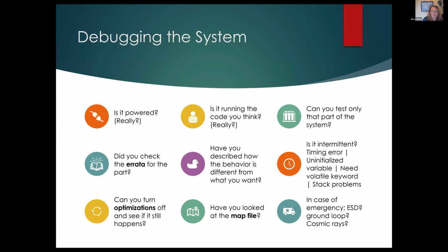My version of a Cortex M0 Plus system was not going to work for that, because any change they wanted to make was going to have to go through me, through the code. And so I set them up with a Cortex M4, so like a much bigger processor, about 4 times the expense. And then we ran MicroPython on it, because the scientists could program in Python.